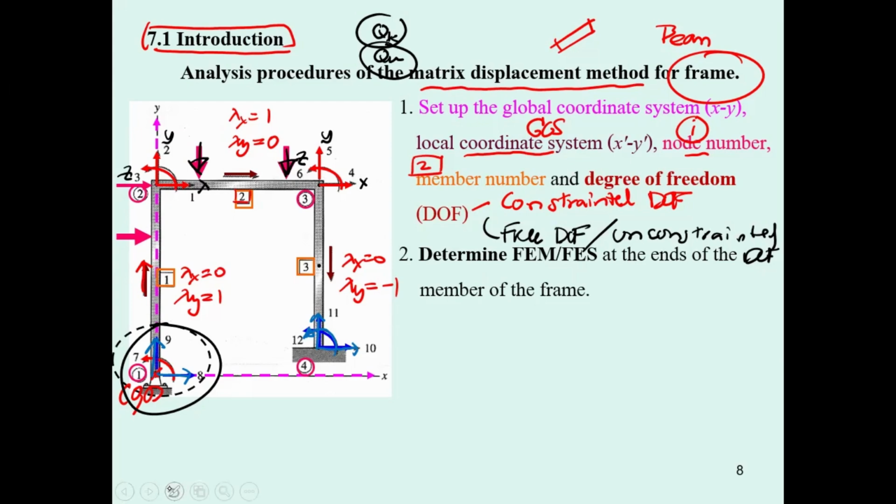Ajahn will provide you again with some equations for the fixed end moment. From the fixed end moment table, you should be able to determine the fixed end shear. We will talk about this later. But the table that you use in the slope deflection equation has no fixed end shear, so you have to determine it by yourself. Then that is applied at the end of the member of the frame. Go back to the truss: the Q sub K is applied at the nodes of the structure.